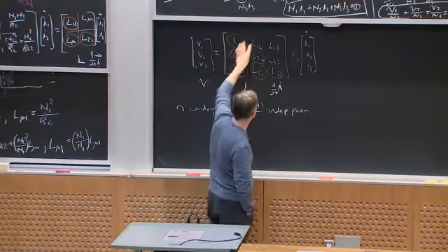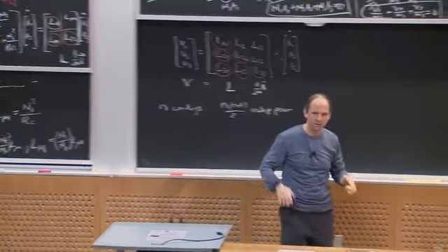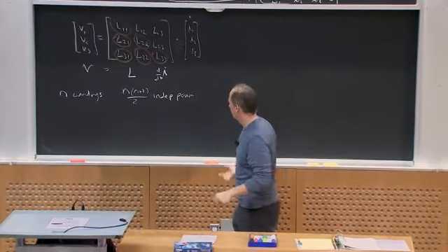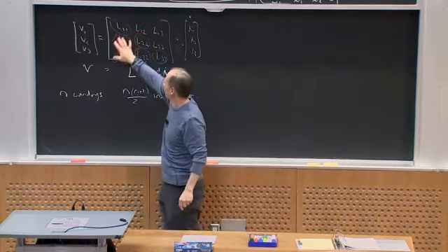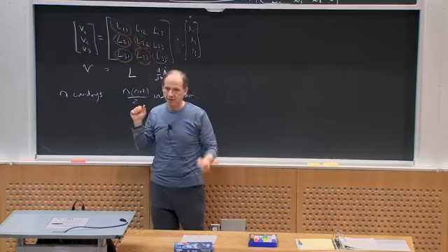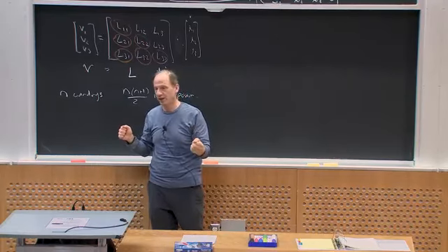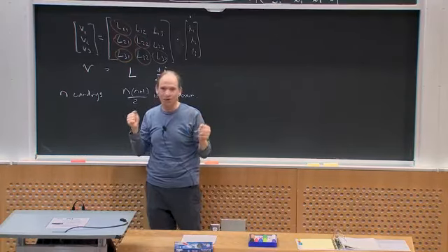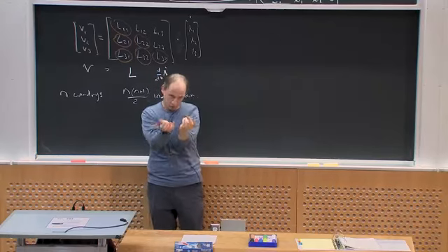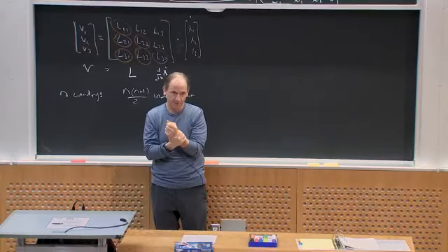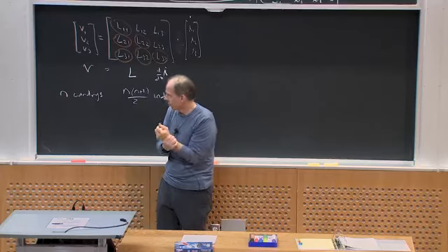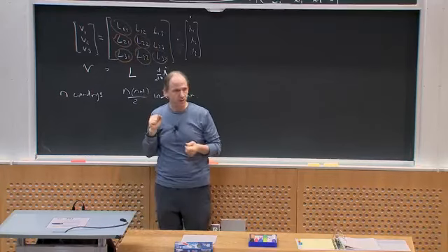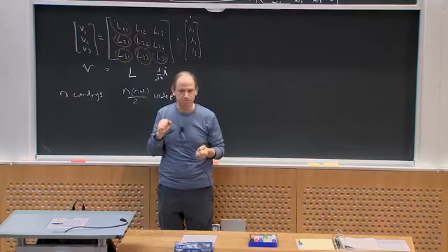I can do a bunch of measurements on my device and figure out what these independent parameters are. That can be tricky. If you don't do it carefully, you'll get stuff that's not quite right. But you can get the terminal relationships. And so I can always get the inductance matrix by doing measurements on a given device.